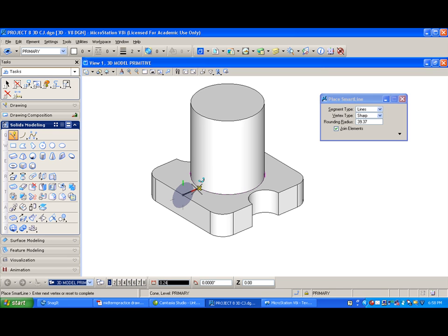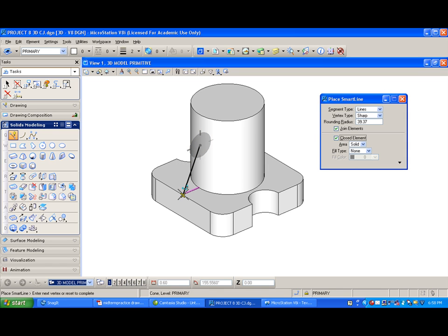See how it rotates my compass up? And I'm going to go in a distance of 0.25. We're going to go up a distance of, make sure you're on, and it's up 0.55 inches. And then just come back down and connect to the original point.